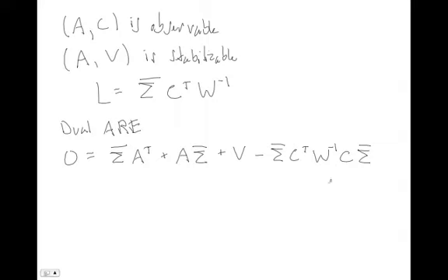And so for this equation, there's going to be a unique solution for sigma bar. You solve that numerically, and MATLAB has tools to do that, such as the function ARE in MATLAB. So you numerically solve for this unique solution for the sigma bar matrix, and then you use that solution to compute the optimal gains L.